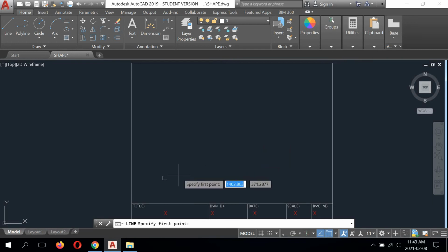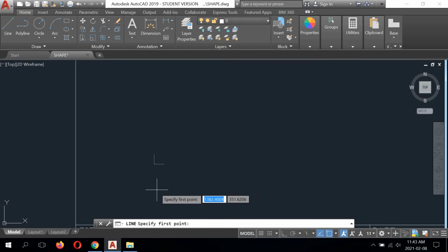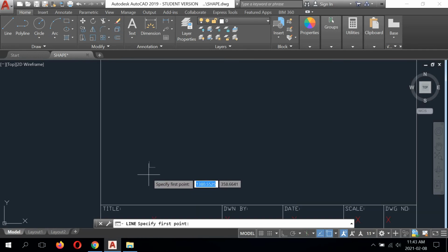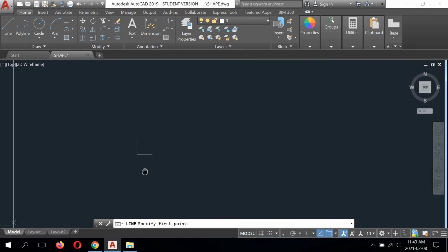So I'm going to zoom in to this little L here. You can use the wheel on your mouse: wheeling forward zooms you in, and wheeling backwards will zoom you out. If I just float my cursor around this, not pressing anything, these little snaps start to show up.